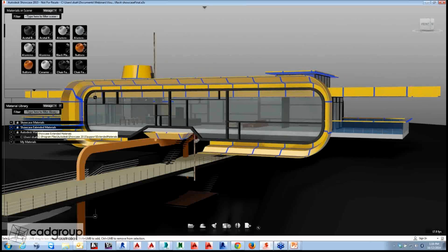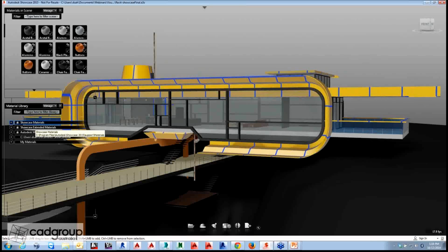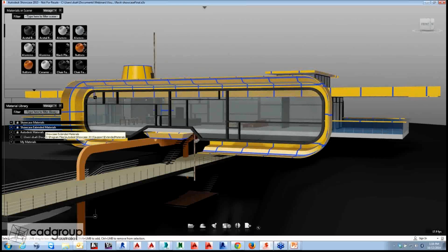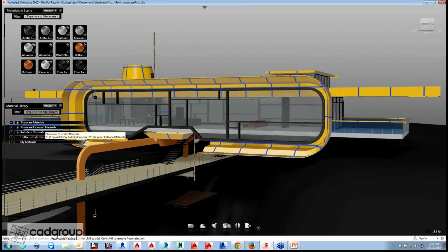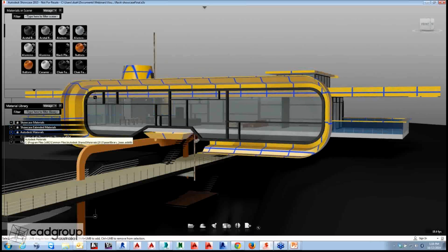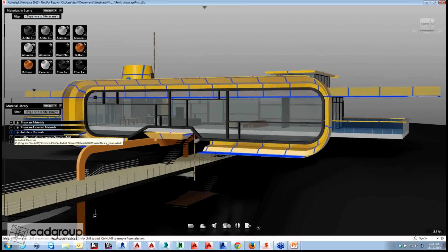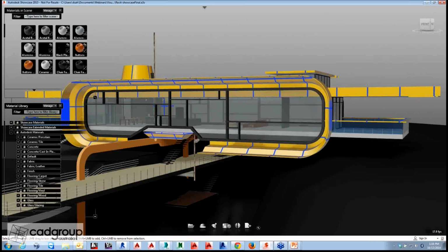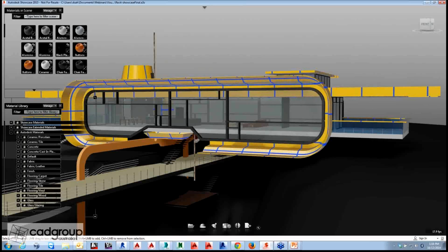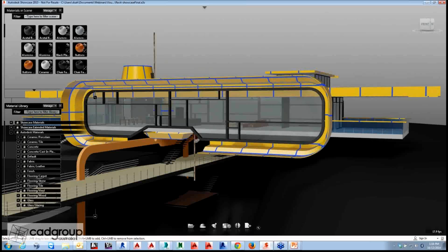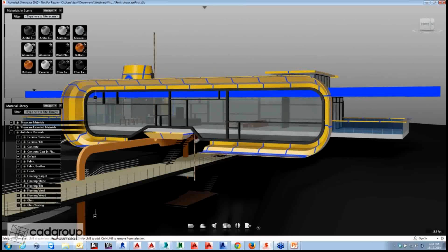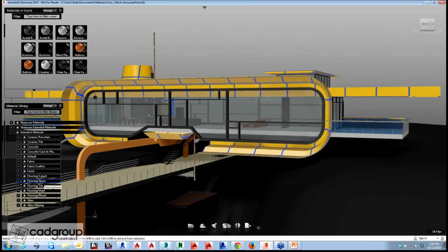or we can use one from the material library. Now in the material library inside Showcase, there are Showcase predefined materials, called Showcase materials, and they have something called Showcase extended materials, which is extended especially for Autodesk software. As well, they have another library called Autodesk materials, which is the similar library as Revit or AutoCAD, and that is the reason why when we use Suite Workflow, it translates all the materials, lighting information, and environment 100% from the design software to Showcase.